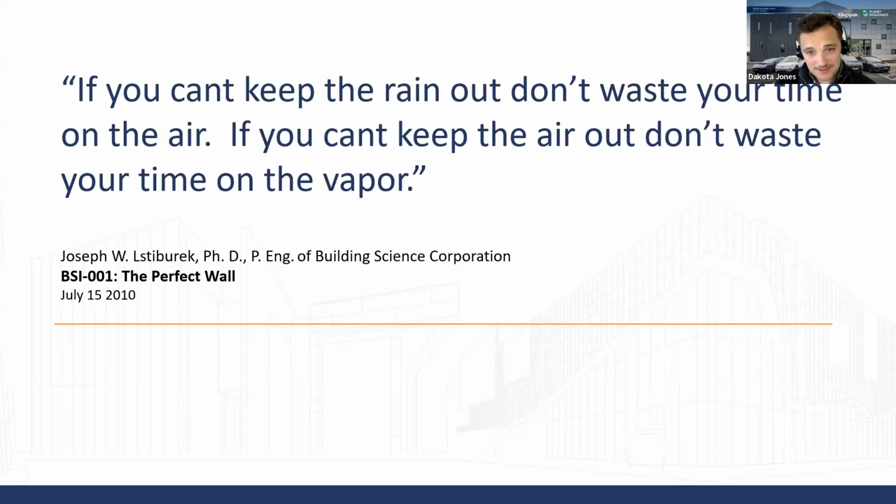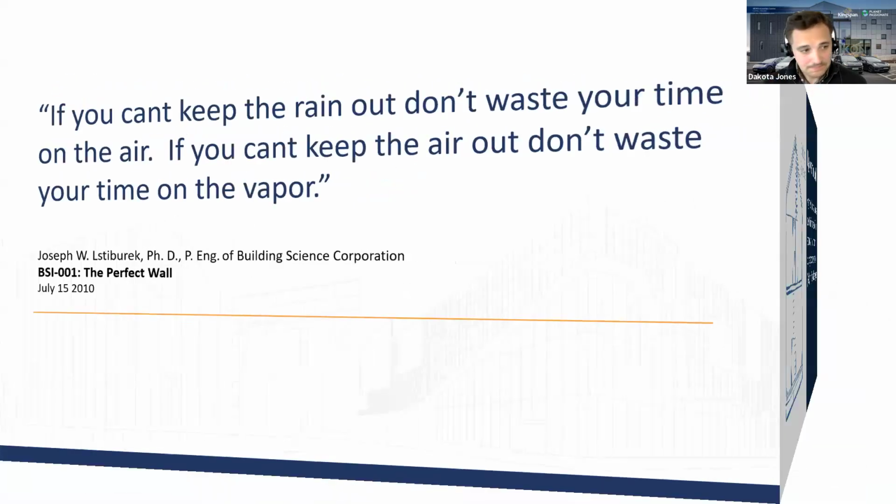Additionally, on a more micro scale, the chimney is pretty obvious, but take these historically preserved wooden windows, like the ones to my right here in my home that rattle all the time, right? If we have a bunch of air infiltration, do we really need to worry about a vapor barrier? We should, for sure, but also it's just going to come in through the shortest resistance area, which is going to be those leaky, creaky windows. So again, holistic. This is not just the opaque surfaces, it's the transparent surfaces and the joinery specifically.